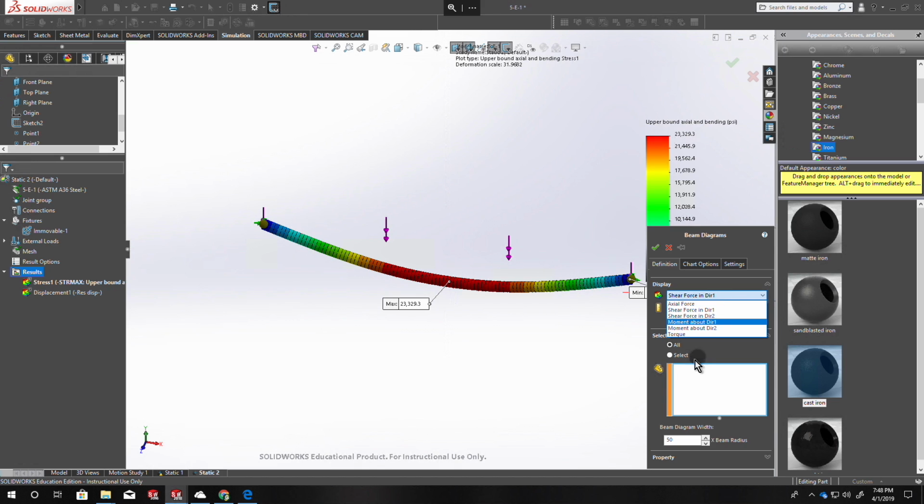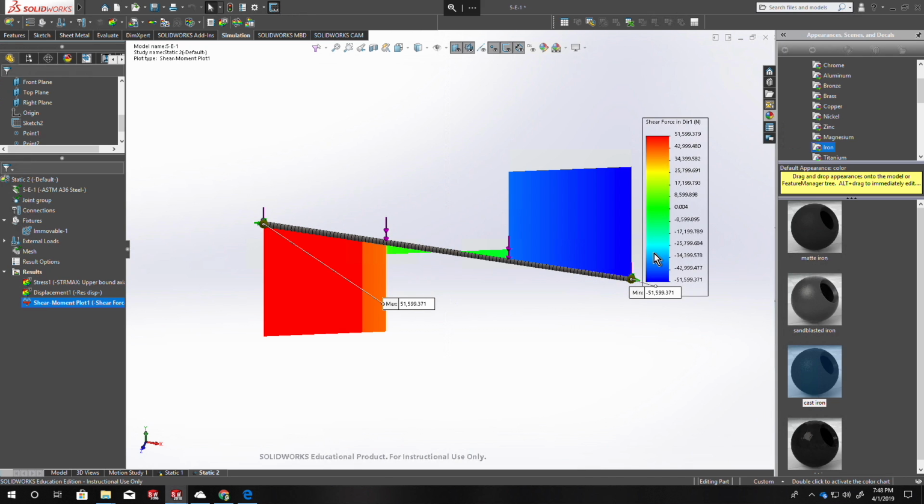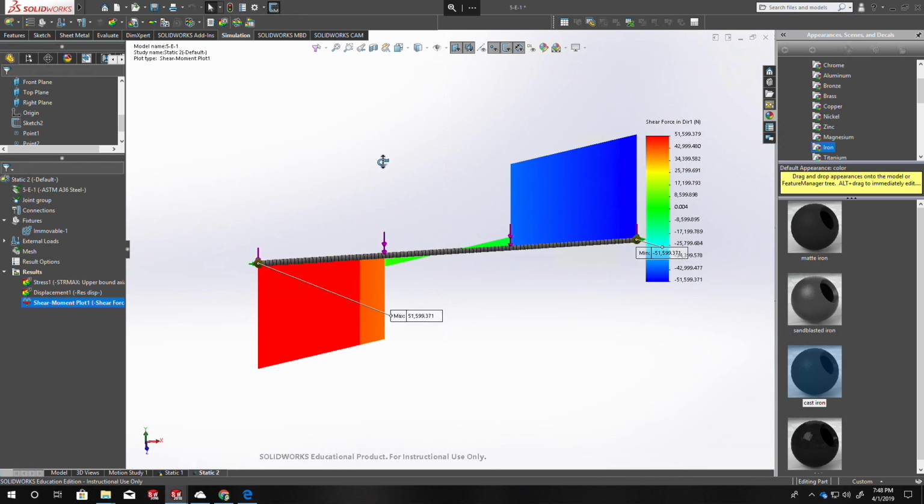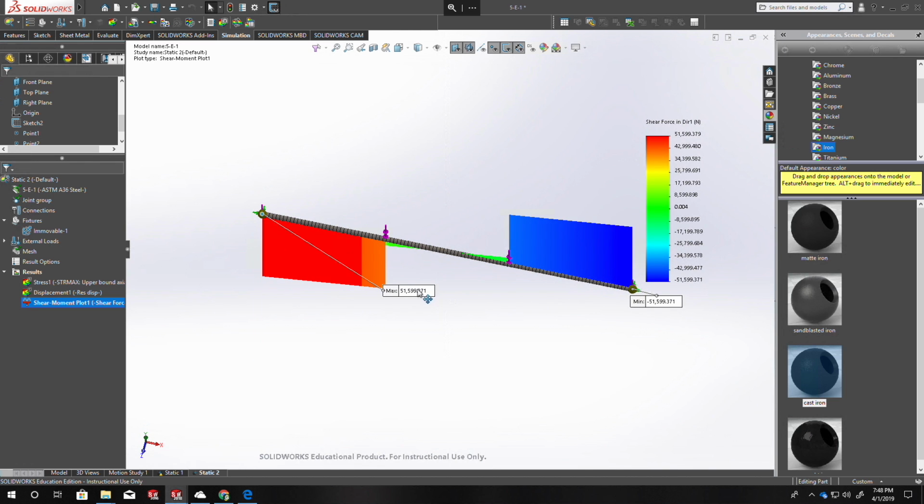shear and moment diagrams to double check that side of your work, but when you're working through these problems, all I need is the maximum moment, the section modulus, and the beam selection. So if you have any questions, let me know. I can make another video or obviously walk you through it during class.